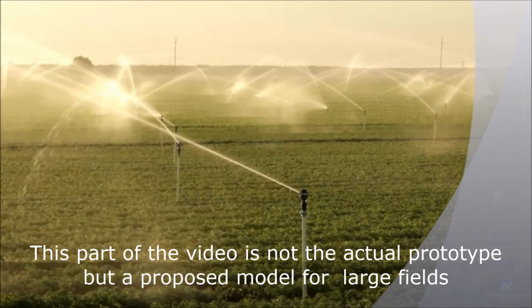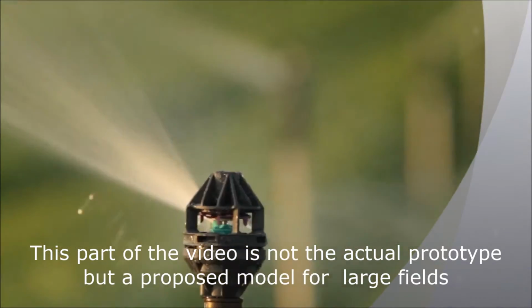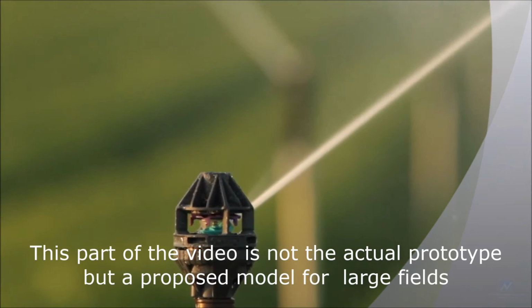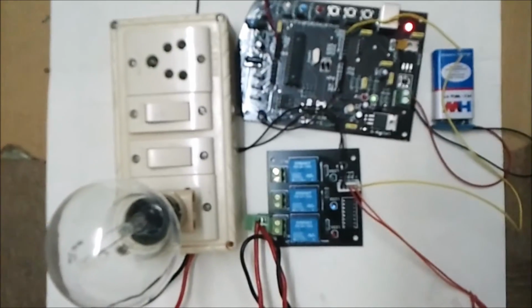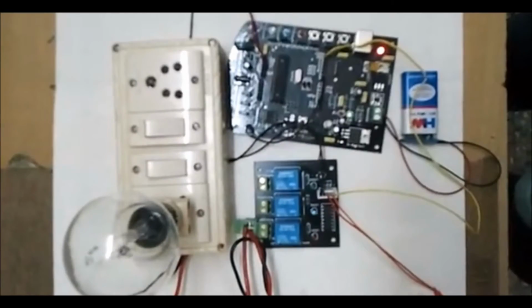The relative humidity in the air can affect the flow of water through the plant. The higher the relative humidity, the slower the transpiration. Hence, the sprayer system is used to increase the humidity, thereby reducing transpiration. The artificial lighting system is based on the LDR input from the field. This is again triggered with the help of a relay connected to the control level. Although we had used normal light for our prototype, the use of glow light, which emits the electromagnetic spectrum appropriate for photosynthesis, can increase the fertility of the crop.